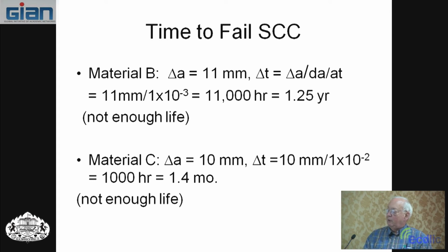And material C would grow only 10 millimeters, and due to its growth rate being faster, it would give only a little more than a month. So I concluded that once you get to stress corrosion cracking, you don't have enough life to really last.